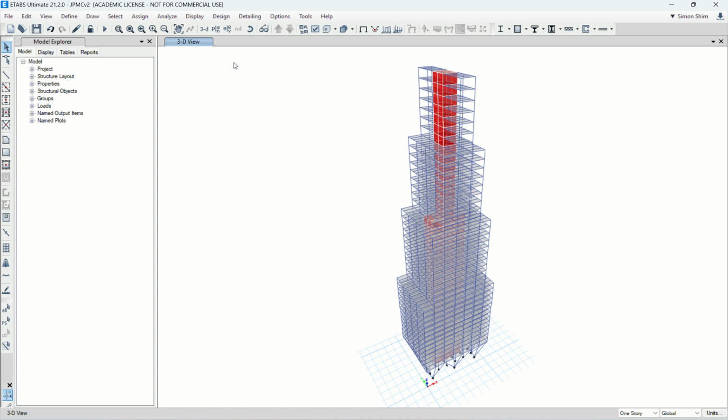So again, we try to minimize the computation effort, so that all theoretical significance or non-significance we need is implemented in our modeling. I think this is very important, because since we assign all the nodes at each elevation to a diaphragm, it saves a lot of computation time.